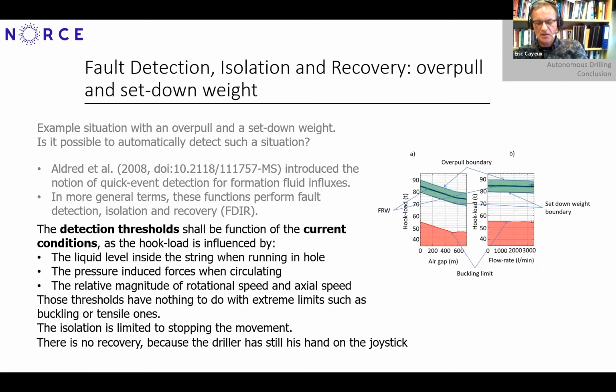And I can just mention that just a couple of weeks ago, there was an operation where this type of technology was used, and during one single day, this type of FTIR, that was a pump pressure protection, triggered 17 times during a day. And each of those times, they saved the well. Then they did manage to get out of the situation and continue drilling as before. But human beings wouldn't have managed to react as quickly to avoid those situations. And that happened 17 times in one single day.